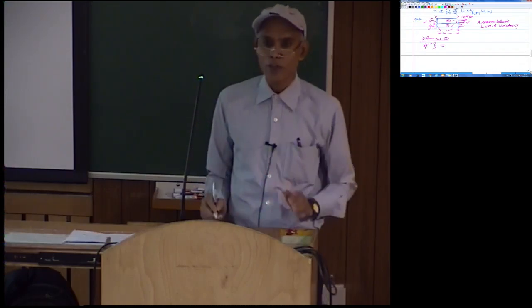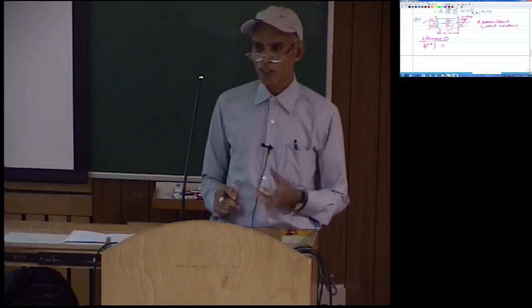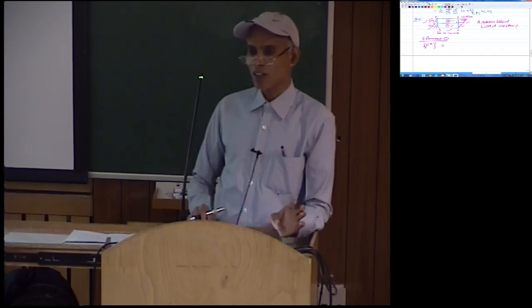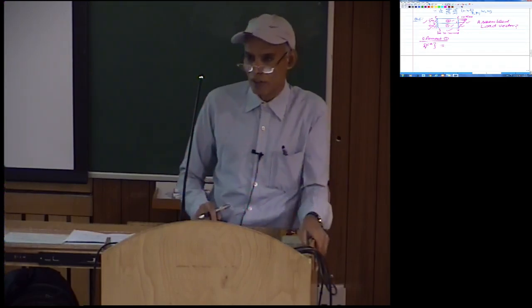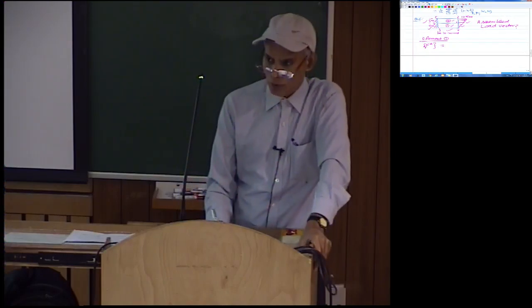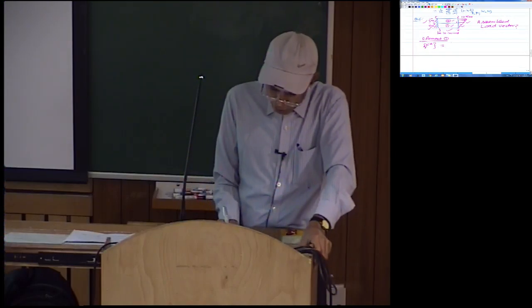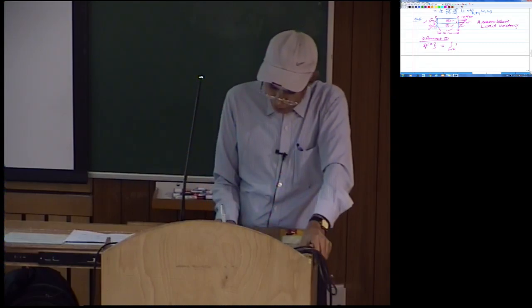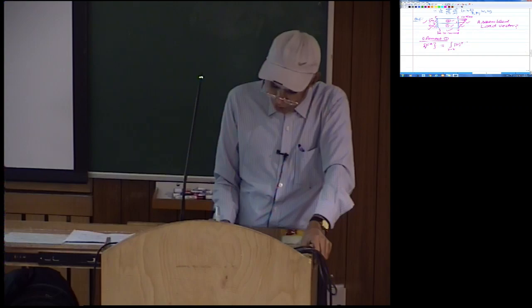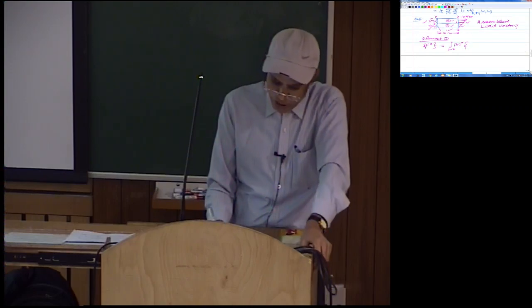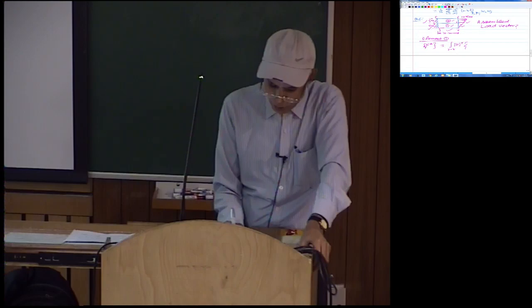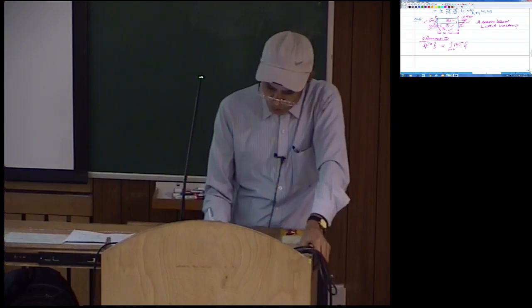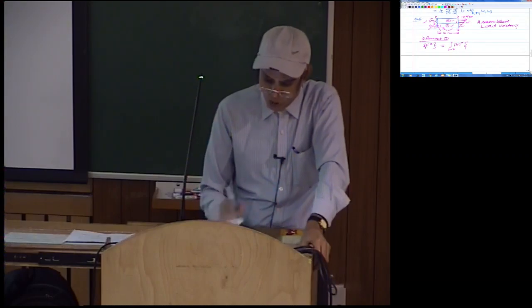Now how do we write this? It's again a 2D problem, so we will have two displacements. When you consider the potential, it is going to be U V transpose into Fx Fy. Since Fy is 0, it's only Fx. So this load vector is again the integration over edge 2 to 4, in terms of nodes 2 and 4, of H transpose and the load distribution along the x direction. It is a linear function of y, as you see here. If I take physical coordinates x and y here, the y coordinate is 10, and the load is also 10.